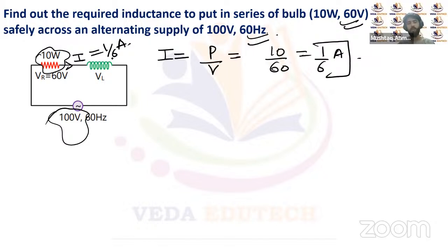And this current will be an RMS value of the current, because in an AC circuit the current continuously varies. So if this is the RMS value of the current, we can write that VRMS is equal to IRMS into the total impedance of the circuit, that is Z.